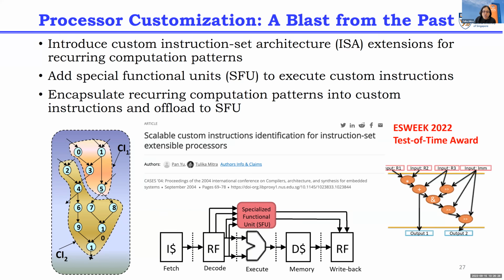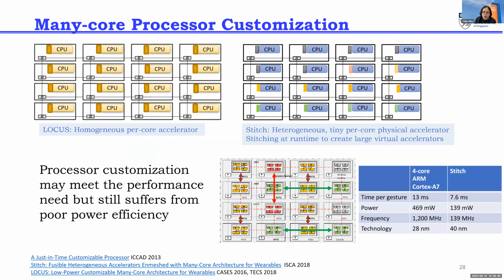So this way you can benefit significantly in terms of performance and power, because instead of fetching and executing 4 instructions over here, you are just fetching one big instruction with a much reduced latency. Now, this is one approach of getting the balance between the specialization and customization.